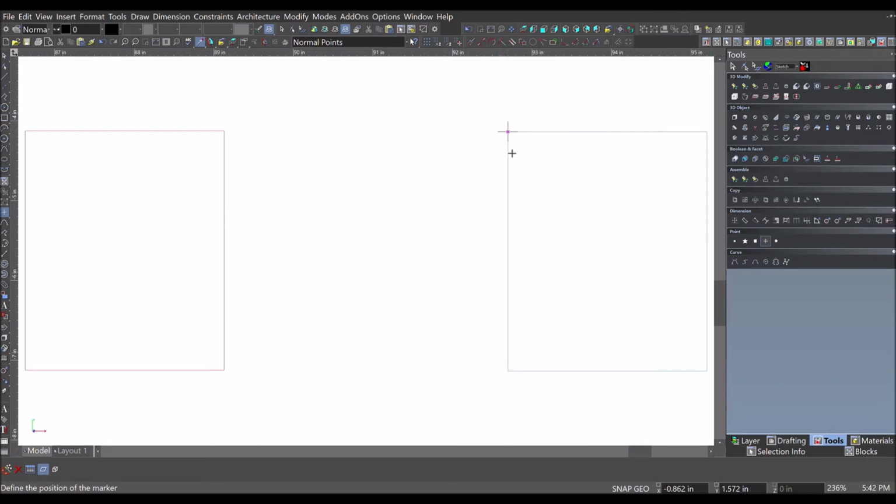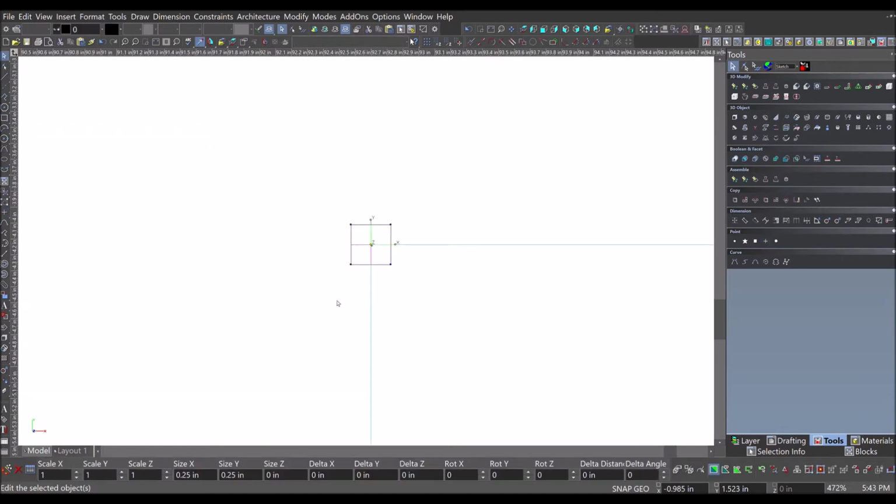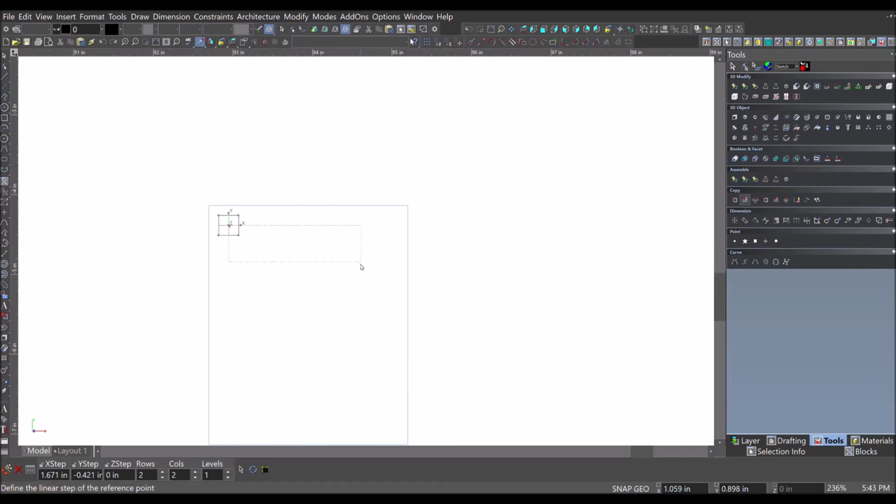In TurboCAD, to do a tapped hole, I take a point and I locate it, and then once those points are located where they're supposed to be, I set up the diameter of the hole, the depth of the hole, the thread pitch, and how far the threads need to go into the hole. All that's done, and you won't see me doing it because it's in a drop-down menu. But then I'll click on each point, and you will see the threaded hole appear.